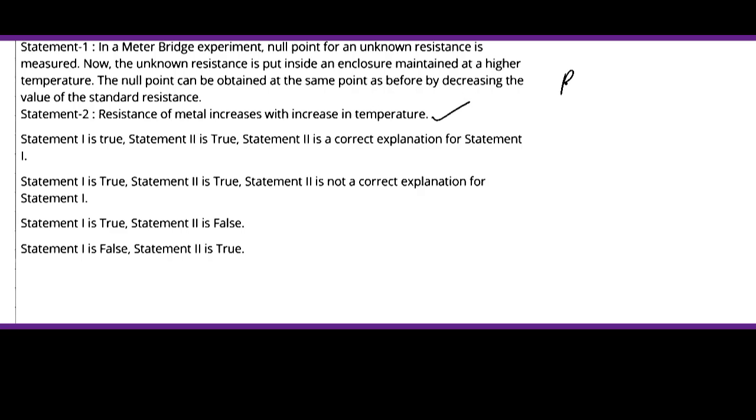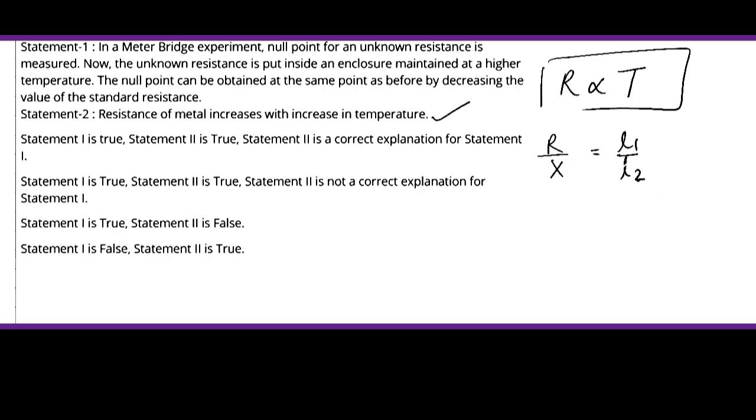Yes, since resistance increases with temperature, the resistance increases. So R by X, at the null point, is equal to L1 by L2. The null point should not be changed according to this, so R by X also should not change.